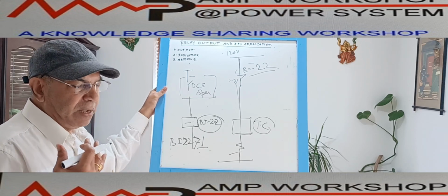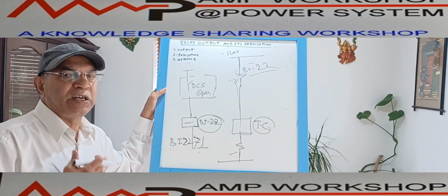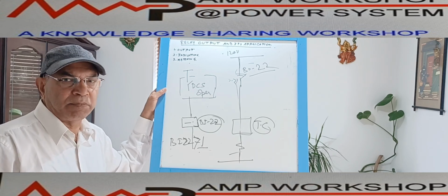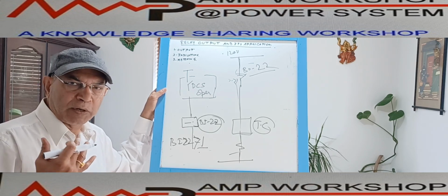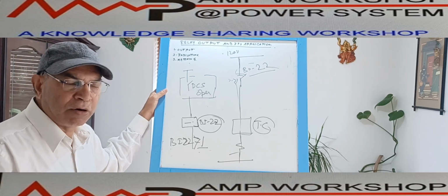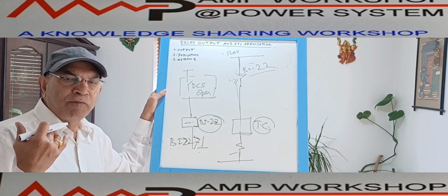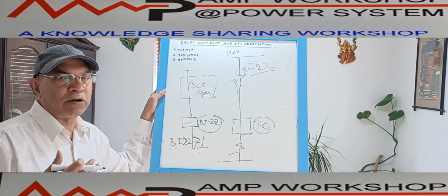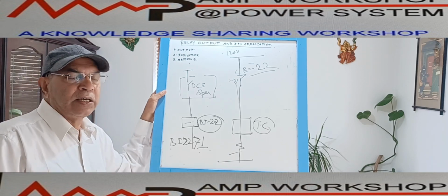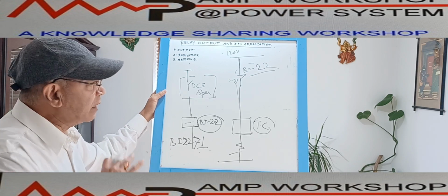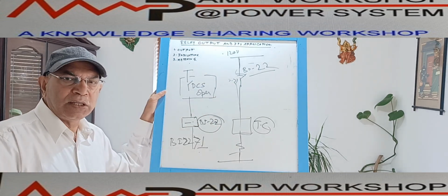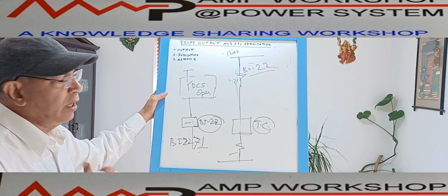this main intelligent relay binary output has different applications. We can use it for multiplication of the contacts of various functions of the switchgear. It can be used for alarm indication purposes. It can be used for tripping through the lockout relay. It can be used for simplifying or multiplying protection functions for other applications. It can be used for breaker closing and breaker tripping. These are the various applications of the output contact of the relay, and these are wired up in this way. So these are the interface of the protection relay output contacts with the switchgear.